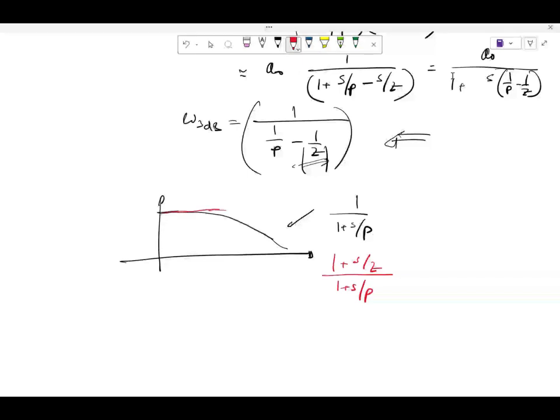How far it will go up and down is dependent upon the value of Z, but I'm going to probably get something like this. And this is independent of the polarity of Z. Correct? So regardless of whether I have a right half plane zero or left half plane zero, I'm always going to get increased bandwidth. Right?